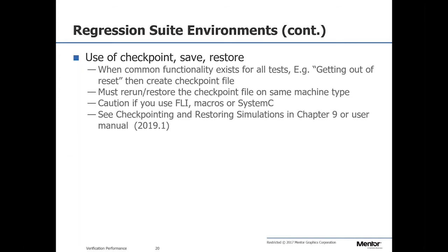Another thing that can save you time is using the built-in checkpoint and restore. Checkpoint and restore is a feature of Questa. It is not available in ModelSim, so you need to step up to Questa for it. What it does is allow you to checkpoint your simulation at moments in time, and then at any point you can say vsim -restore that checkpoint, and then reload that checkpoint and simulate on from there.